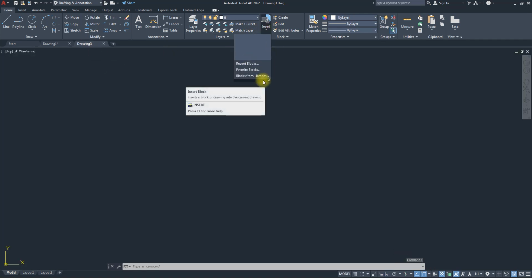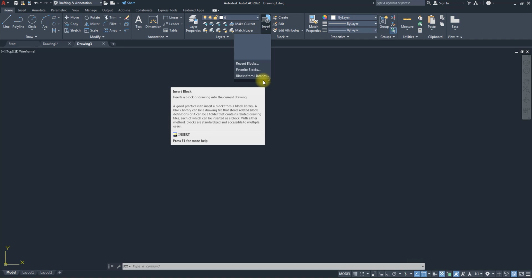So what does that say? It says that whatever block you create is only meant for that particular drawing. As soon as you go to a different drawing, it refreshes, you don't have that block. Do you understand? So how can we do it in such a way that if I create a block, I should be able to even shut down my system, come back later tomorrow, and still reuse that block? Am I making any sense? So how can I do that?